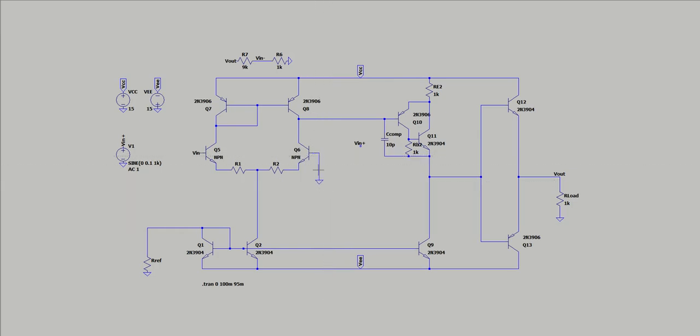So now you want to notice that the positive terminal is to ground and the negative terminal is also to ground. This negative terminal connects to the input resistor and the feedback resistor, which there is no AC source to. So you're going to run the sample,